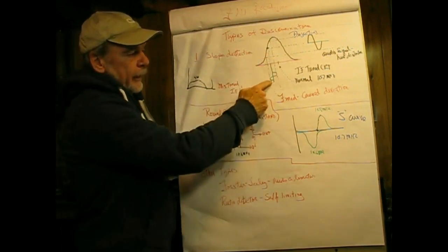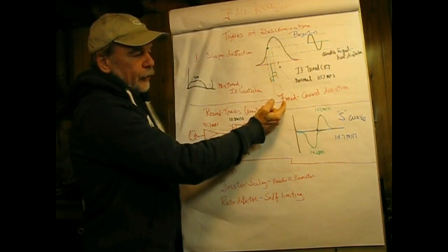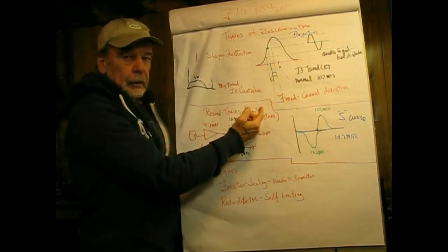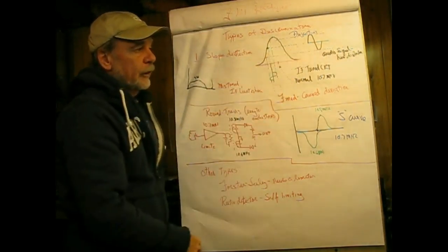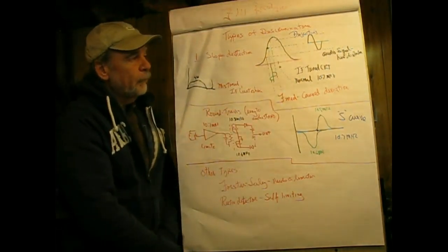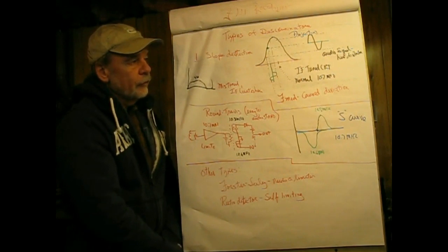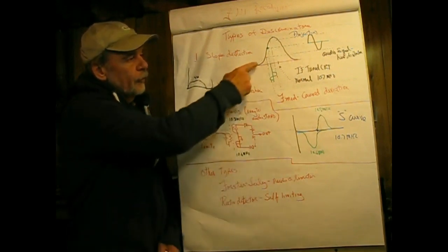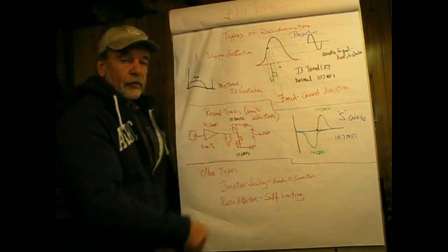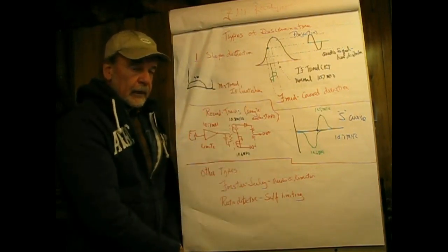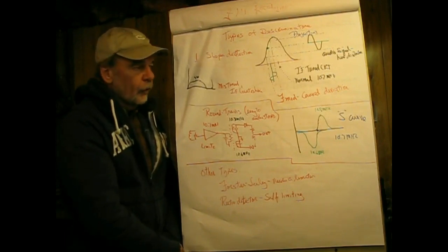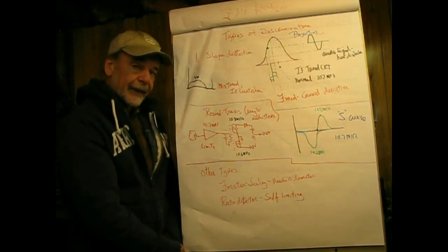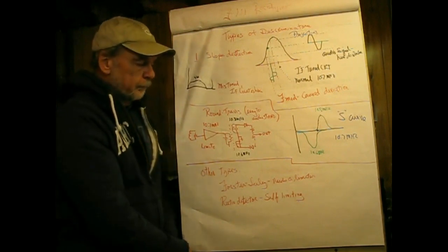And then if I take a sinusoid shown as deviation here and project that onto this slope, what we see is we can recover that signal which caused the deviation as an audio signal. Now the problem with this is this curve from here to here is not straight. And what that means is that the audio coming out is going to have a degree of distortion. So it did work, but further development was needed.